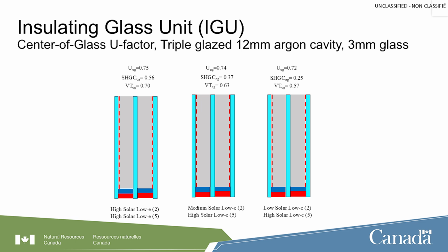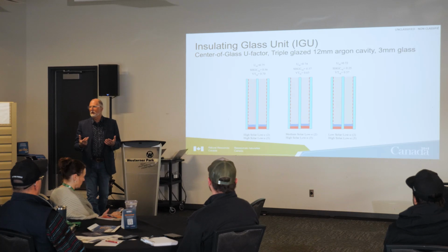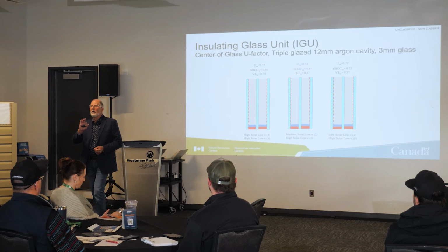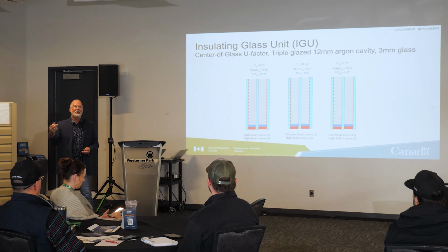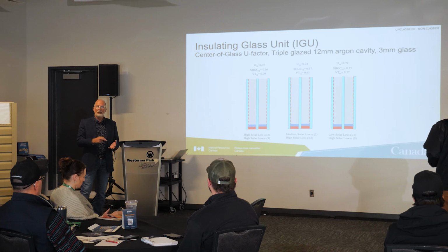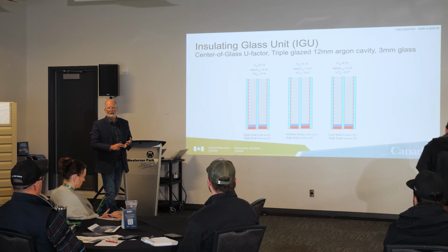So again, if I'm doing a custom home and I'm looking at the overall heat gain and the percentage of glass within there, I want to know how much heat's going to be generated by that glass and where to position that. Because I want that homeowner to feel comfortable. I don't want them to overheat, but in the wintertime, I want them to be warm enough.